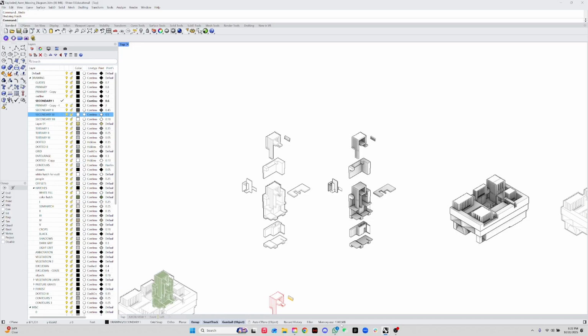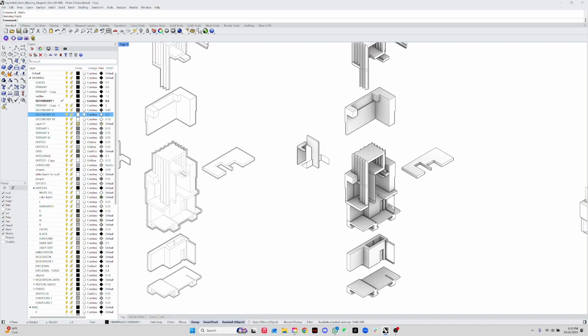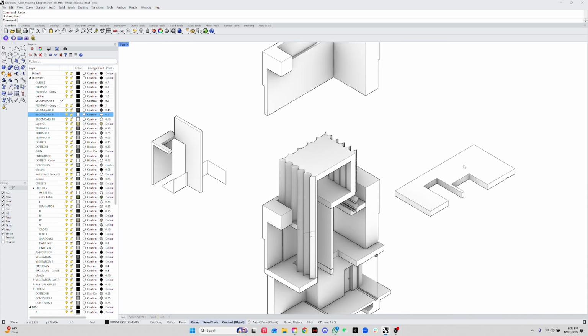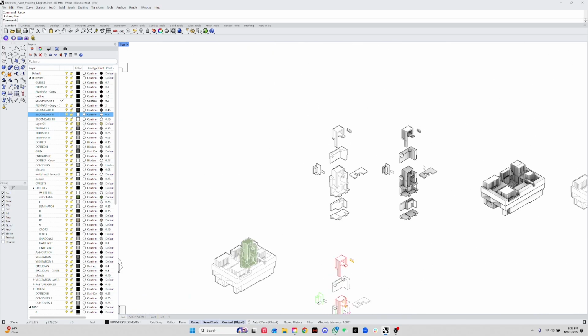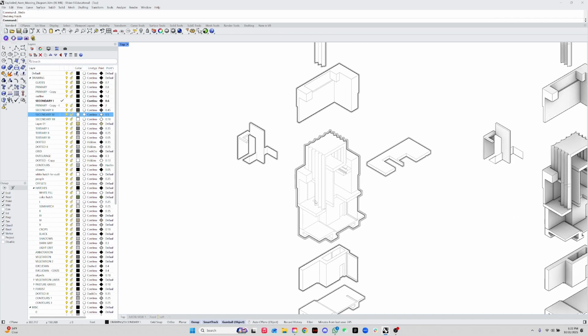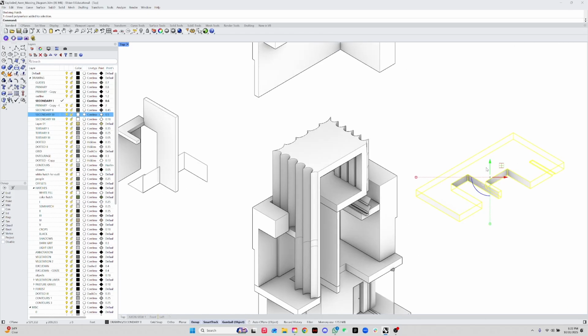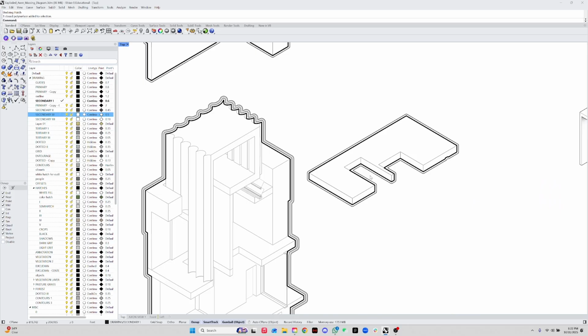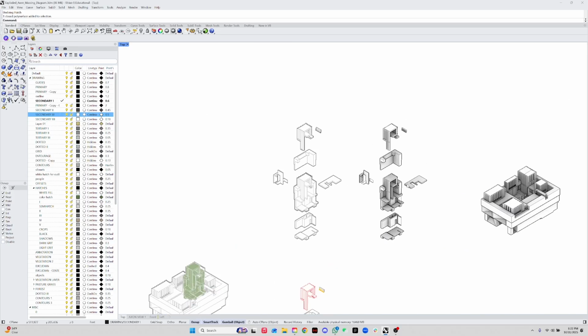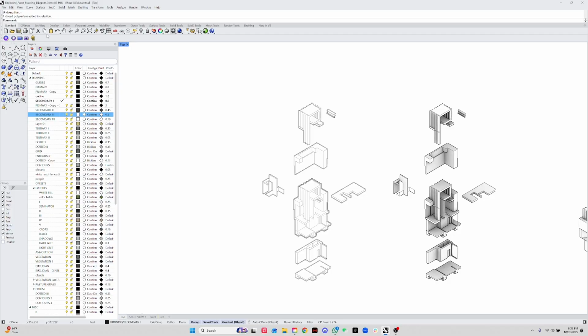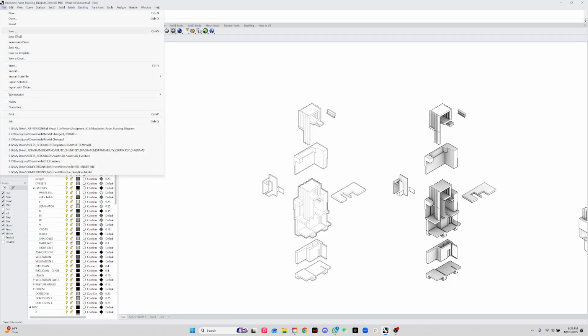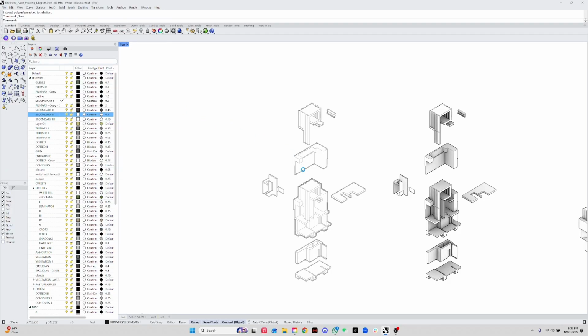The reasoning why we put the model this way is so we can add hatches and then just transfer them to the 2D drawing. We're not gonna make 2D of them. We're not gonna explode them. We're not gonna do anything. We're just gonna apply them in the 3D model, grab them, and put them in the drawing itself. And you're gonna see how that works. So yes, obviously save your file if you have that. Make sure you save your stuff.